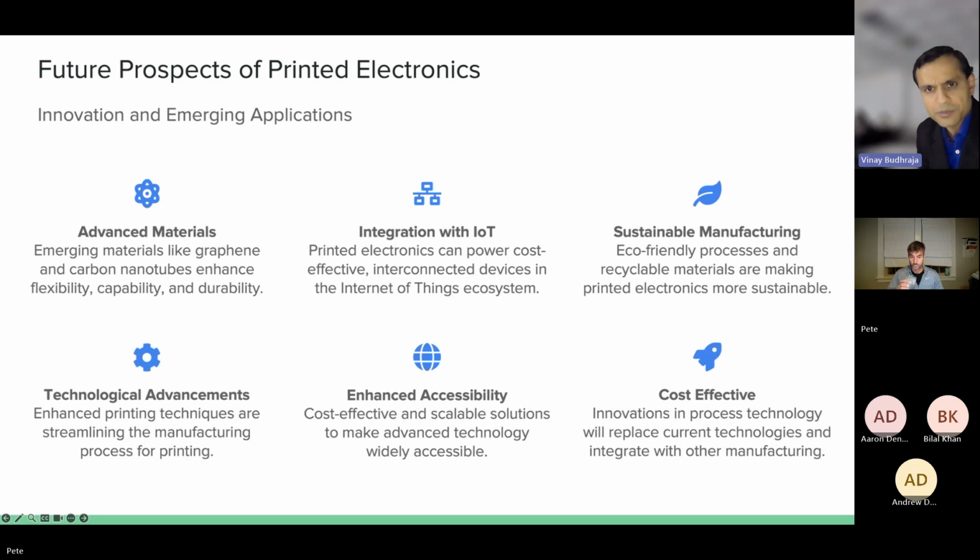Okay, good. So your system, the microplotter, is a hybrid between inkjet printing and direct writing, right? What are the advantage features of the microplotter over inkjet? Yes, that's correct. We're a hybrid approach. While we utilize ultrasonics like an inkjet, we're not forcibly ejecting the droplets out.